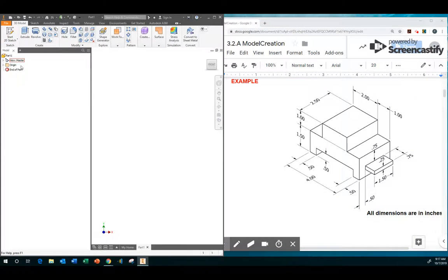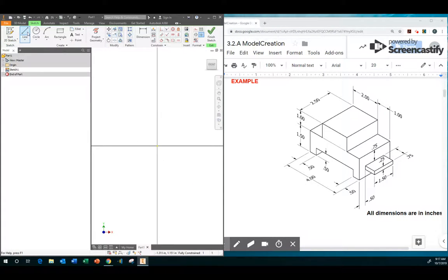Okay, so I'm going to start 2D sketch. So my browser is open, my tabs are open, 3D model tab is available. I'm going to click the command start 2D sketch. I'm going to start with the XY plane. And then instead of going back later, I'm going to go ahead and start at the origin. And what I'm going to do is draw a line up. Once it's at 90, you'll notice that there's a blue highlighted 0.313. I want this, so I'm going to start drawing this first leg. I want it to be 1.5, so I'm literally going to type in 1.5.